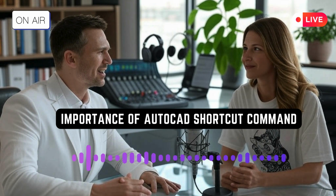So it's in the Customize User Interface Editor, also known as CUI. It might be a little hidden, but once you find it, it's like having your own shortcut workshop. And you can go in there and assign any keyboard combination to any command. Oh, that sounds awesome. Yeah, I can already imagine making shortcuts for all kinds of stuff.